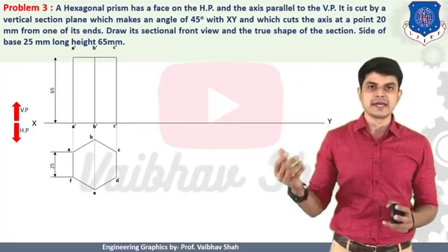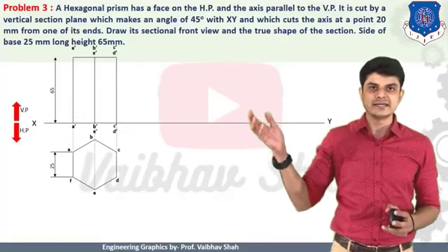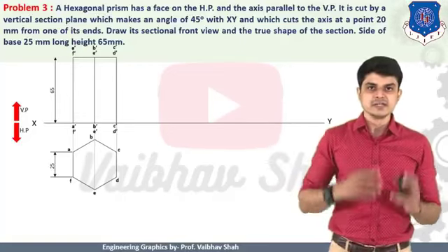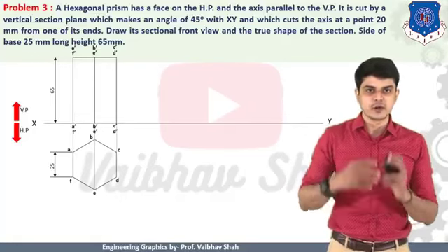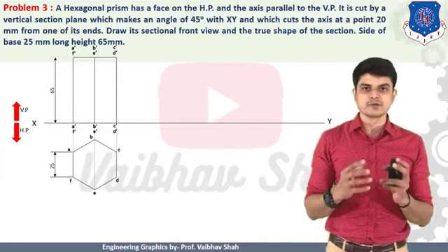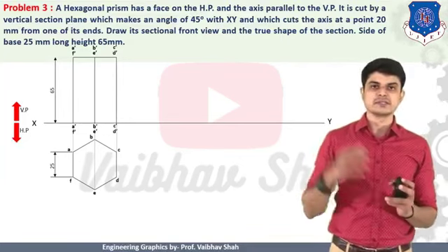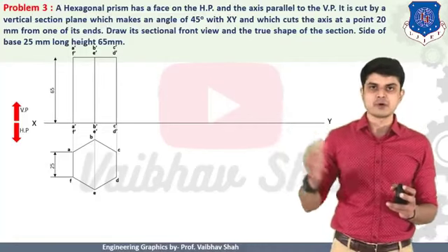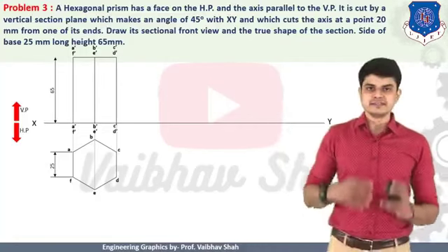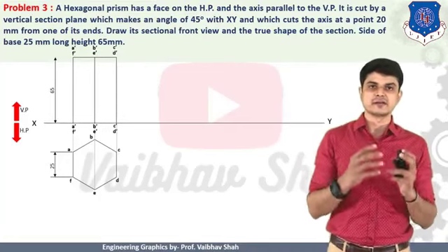Then we should come back and define this line as D dash D dash, then E dash E dash, and then F dash F dash. So this is nothing but a hexagonal prism, and always remember, a hexagonal prism has two of its edges superimposed or coinciding with each other, so we'll have a double dimension to its sides, the top face and the bottom face dimensions. Now, in the second phase, it is said that it is resting on one of its rectangular faces.